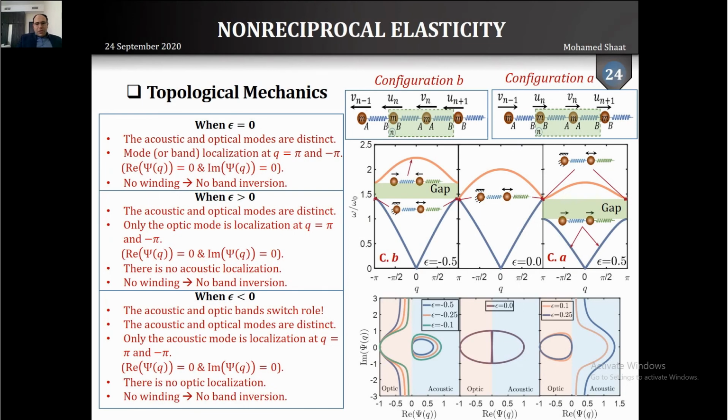Then I used this metamaterial in monoatomic and diatomic lattices, like the diatomic lattice shown here. Thus, the conventional springs of these lattices have been replaced with this newly developed metamaterial, and these two lattices showed static non-reciprocity when tested under static loads. Also, I investigated the topological mechanics of these lattices, and I found some interesting results as shown here in these two dispersion curves, in addition to the eigenmode representations over the complex plane.